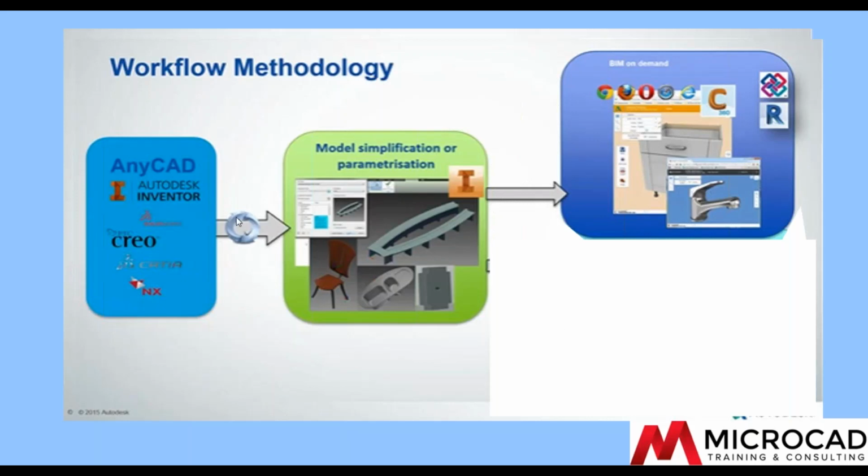In Inventor, the model can be simplified because the architect doesn't want or need excessive detail, and defining parameters can be added. This is then output and published as a Revit family to make it easy for the architect to use. These Revit families can be included on an online catalog. Here, there isn't any data flow from the architect, it's solely from the manufacturer to the architect.